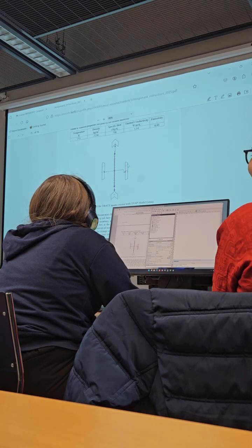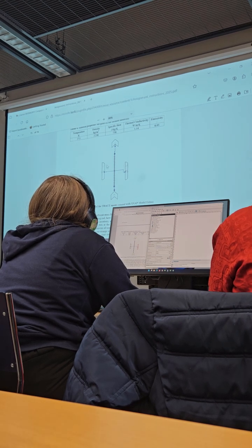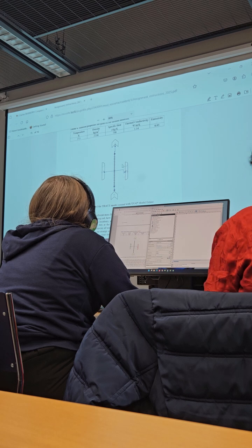I don't know why the colors are different, but still. This heat structure represents the fuel rod inside the glass tube. This heat structure will represent the glass tube wall, which connects to the atmosphere, since we need to take into account the heat transfer between the glass tube and the atmospheric air.